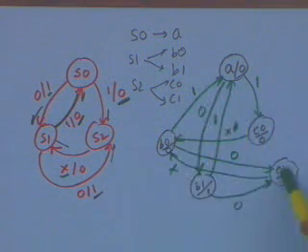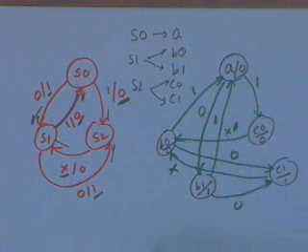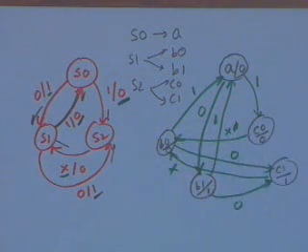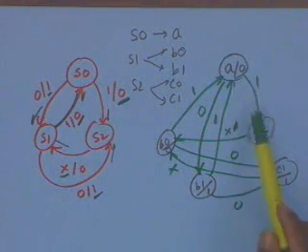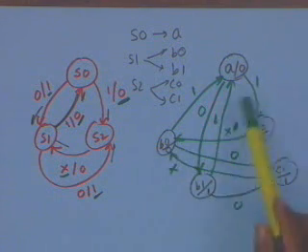I should of course make sure that all the transitions are specified at each state, for all the input combinations. I should have a transition specified, then only it is a deterministic thing, and that I have all the transitions specified, uniquely specified.